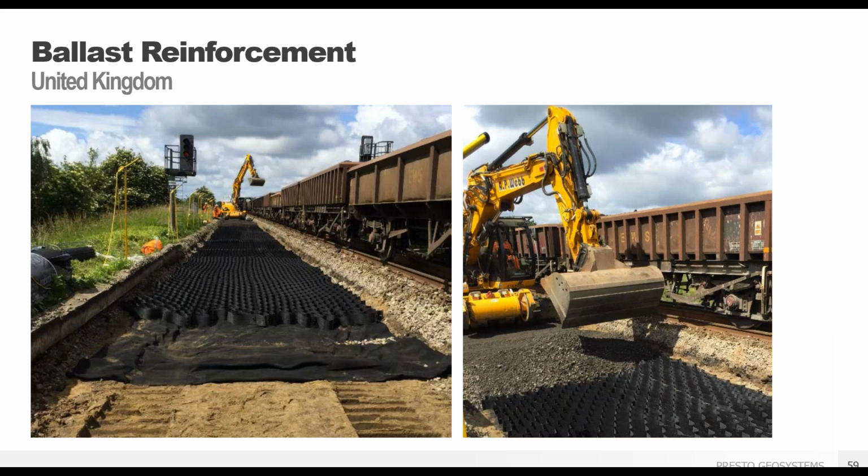So here you can see just a couple images on installation. Here you can see the non-woven geotextile being placed over that sand bed, 150 millimeter, 6-inch GeoWeb panels going down, and basically the contractor just spread it out.